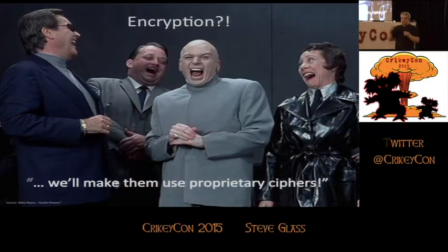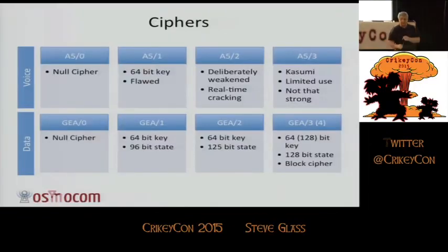The other side was that the mobile system, when they planned in cryptography, was done with a Cold War mindset. Countries like Germany wanted strong cryptography because they didn't want East Germans listening to their mobile telephone messages. They lost out. The British wanted weak cryptography so they could spy on everybody. That's what actually won. So what we have is a series of rather weak ciphers. For voice, we have A5/0 through to A5/3. A5/2 is one designed for export markets, deliberately weak.